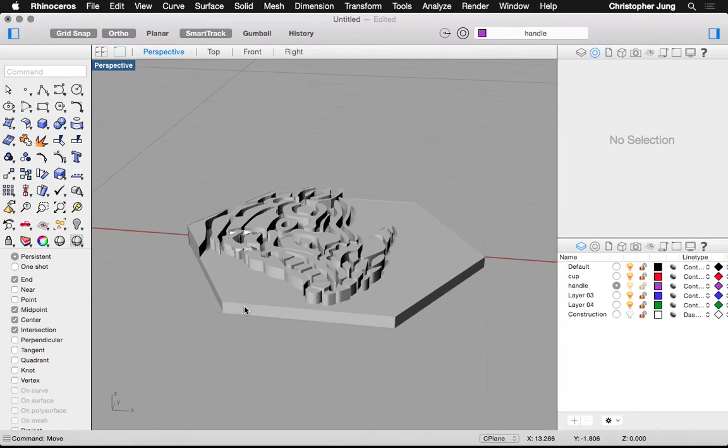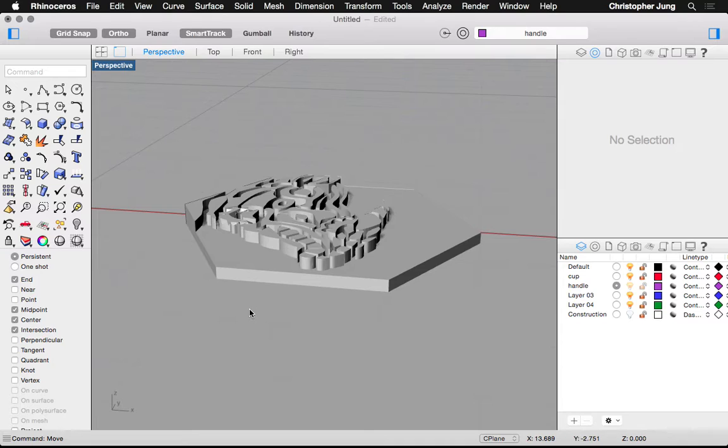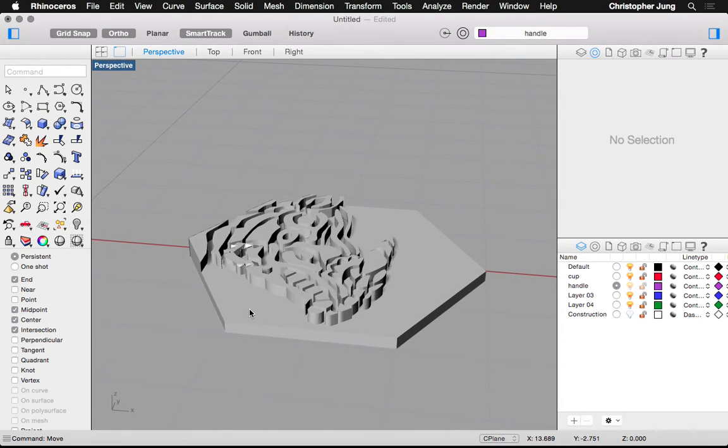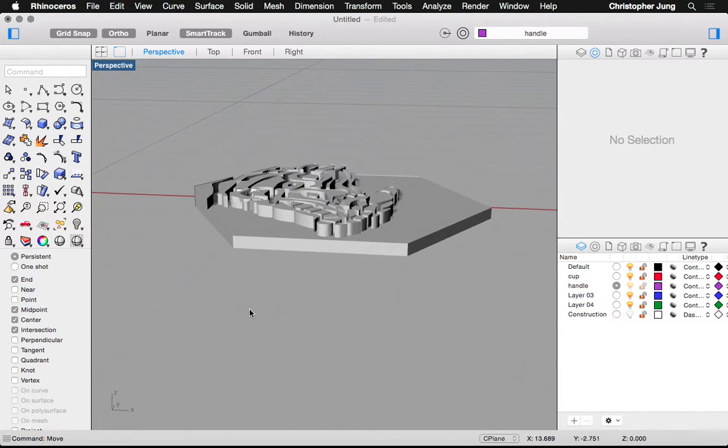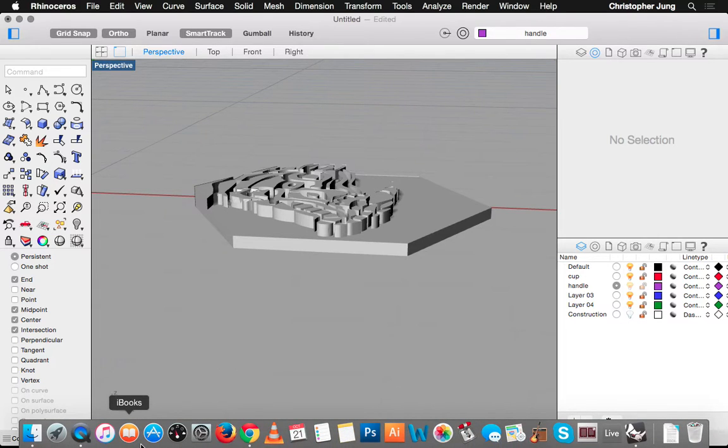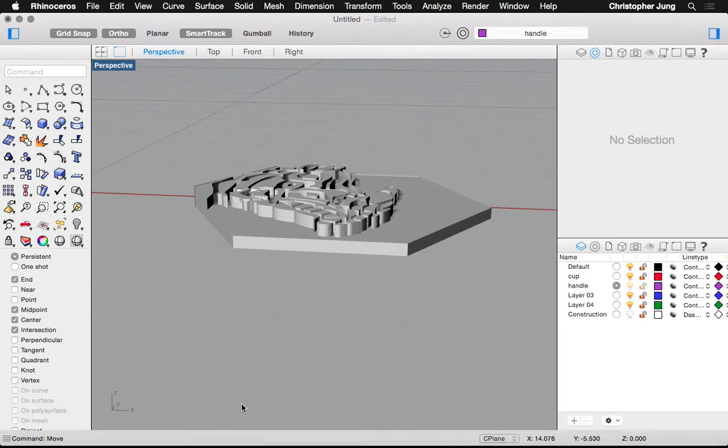In the case of this project, I did a drawing in Illustrator because that's what I'm most comfortable in. I don't do Rhino that well. I imported it to Rhino and extruded it 1 millimeter up, because we're doing these very small objects. I extruded the base 1 millimeter down, and that's why you've got these 2 levels. I made everything into a plane using that surface plane button that we showed. Then I joined it using Boolean difference, and I think that was it. So it could be as simple as that.